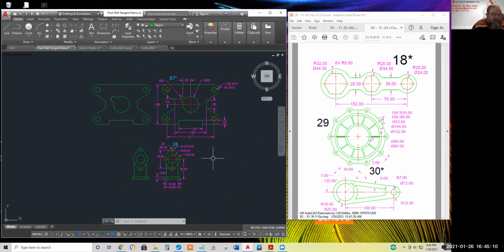Any question about tangent to tangent object snaps? Again, think of fan belts. And when you come up with a tangent, you know, deselect, oh, I left tangent running for some reason there. You'll have tangent alone running.